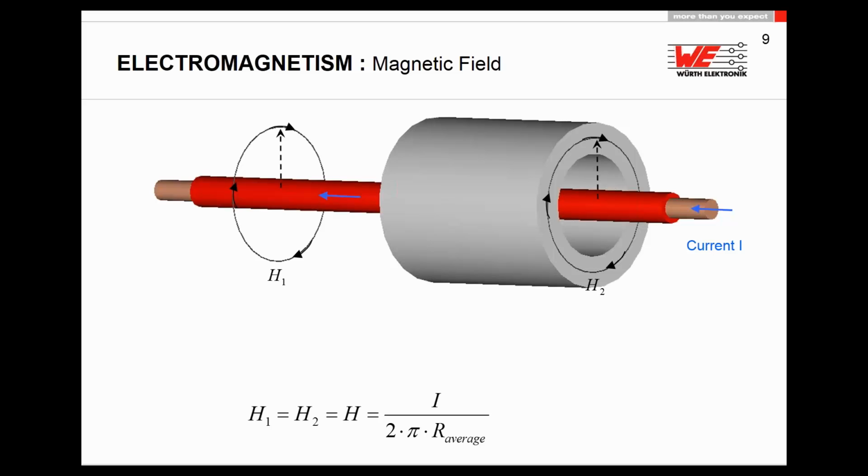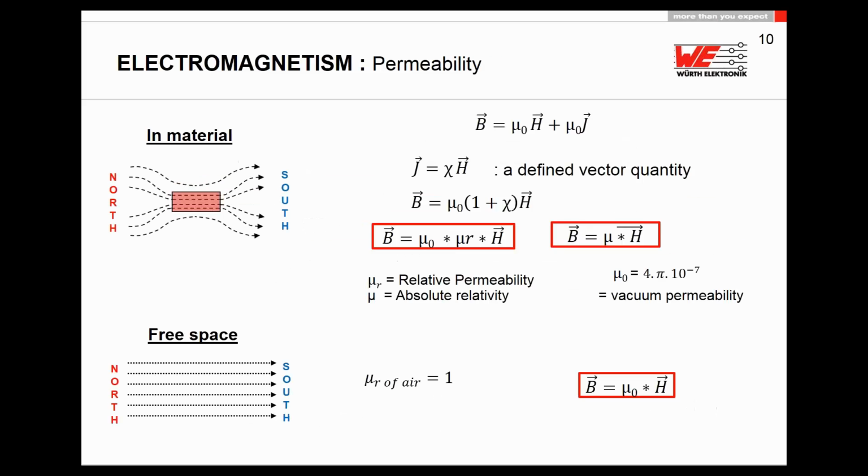It must be real because this is the formula giving and I trust that. But how about the magnetic induction? It's the same as well? Just think about that. It could be different because air is a bad magnetic conductor. As soon as you apply a ferromagnetic material into the magnetic field, this magnetic field will bend. It will take the easier way to couple through.